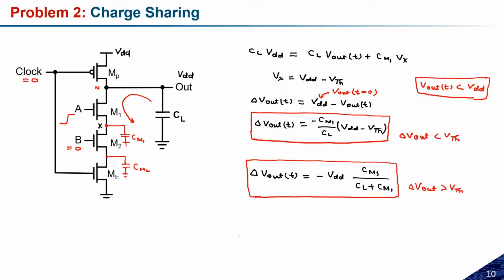Yeah, this is really very important. I think I have already told you in some of the layout designing, when I was designing the two layouts of NOR gate, two kinds of structure, and if there are three paths coming and four paths coming, the diffusion capacitance will be different for each layout. I think you can remember that lecture. So the layout is really very important, how we are making our layout of any particular circuit, and if we are able to make the perfect layout so that we can reduce the diffusion capacitances, then effectively the internal capacitance can also be reduced. So this is really important.